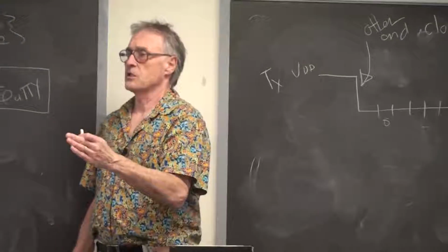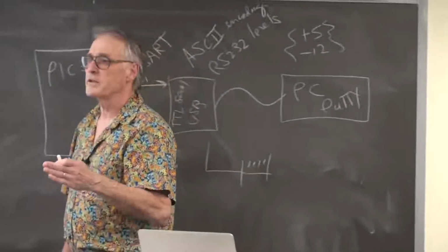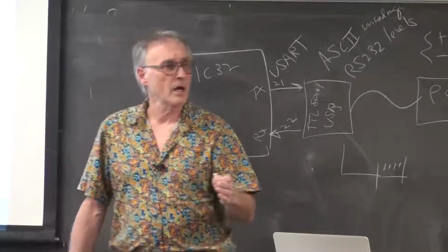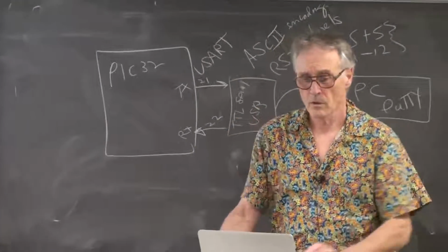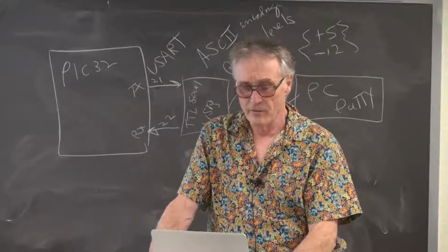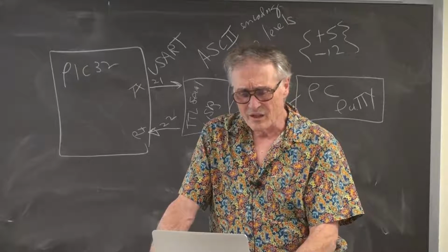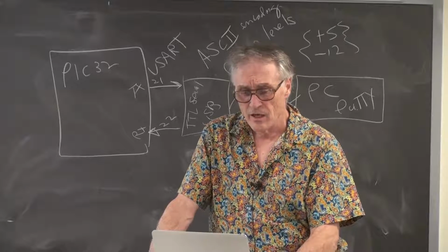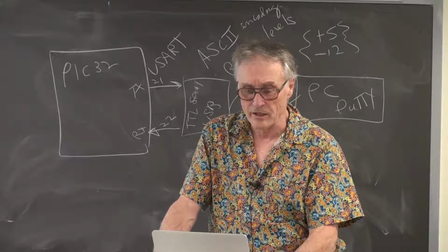But you must set up PuTTY so that the clock rate on PuTTY matches the clock rate on the PIC32. What is the clock rate on the PIC32? Let's go back down to the proto-threads page. I tried to package this up to make it a little bit easier to use.